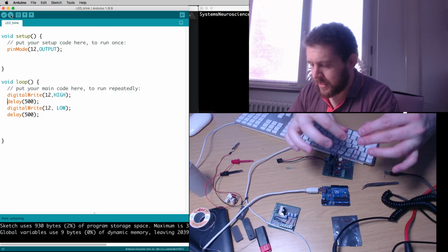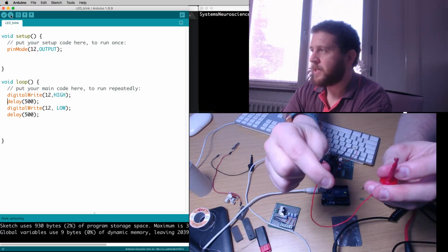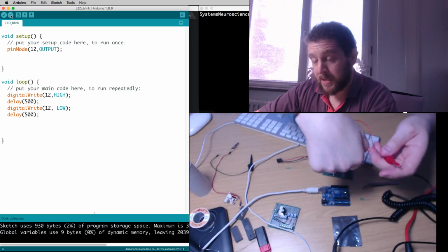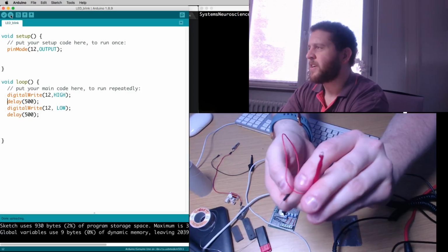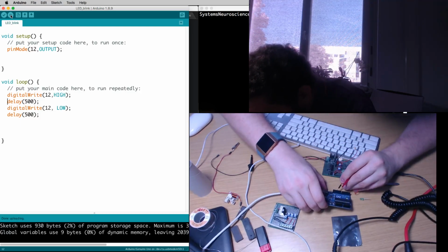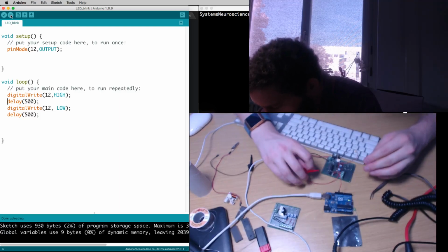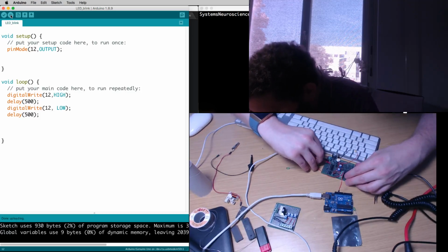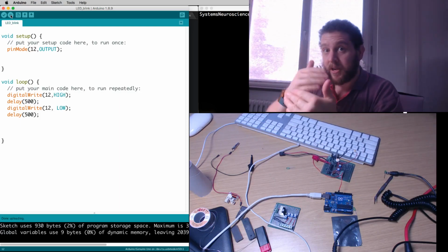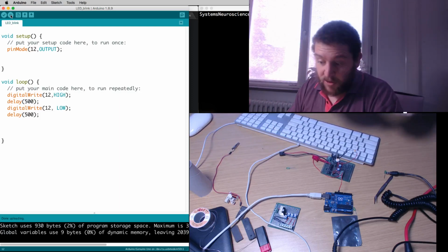So what we'll do is we'll take this out. I've got a cable here that I've created. This here is a pin. I'll just slot that into the pin 12 socket on the Arduino. You can see here I've got a little clamp that I can clamp on. So here I go to pin 12, okay, and then I'll clamp that onto the left hand side of this top transistor. Okay, so this is I think about 7 or 8 transistors back to back to back, and each of them are isolated. So you get 7 switches in one basically.